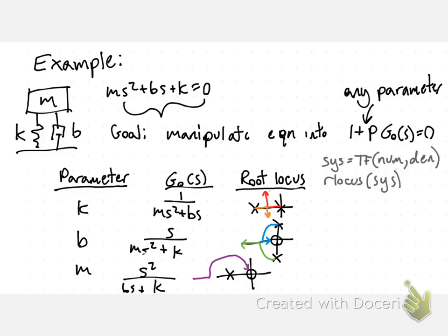0. And then I've used orange before, but I like purple and orange. Then we'll have our other pole start at our open loop pole, and our closed loop pole will, as it increases, meet up with that pole coming in from negative infinity, and then loop around and end at the other zero.